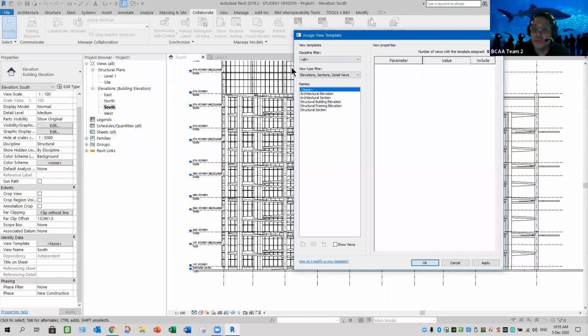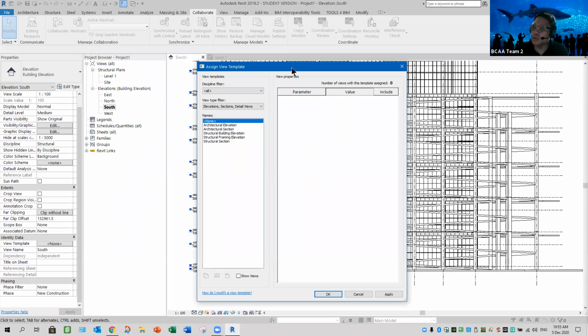Now your tutorial one, we didn't do this, but now we got to learn how to do this. We use visibility of VG or the ad hoc right click thing to do the view management. But if you are having a link model, that means the view you're going to manage is two now, our own view and the Archi model view.